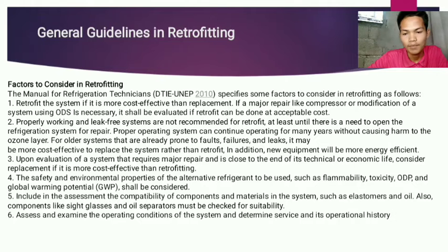Second is proper working and leak-free systems are not recommended for retrofit at least until there is a need to open the refrigeration system for repair. Proper operating systems can continue operating for many years without causing harm to the ozone layer.